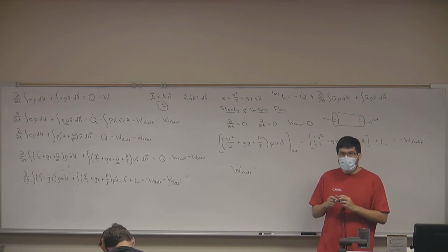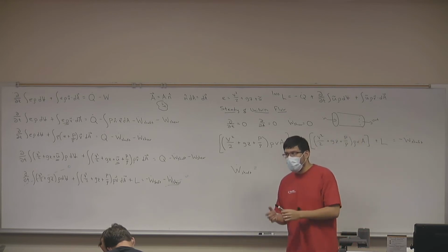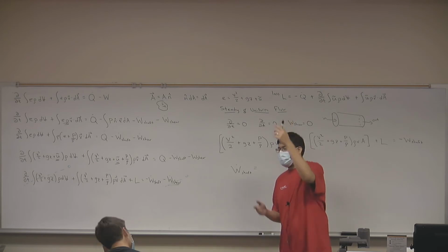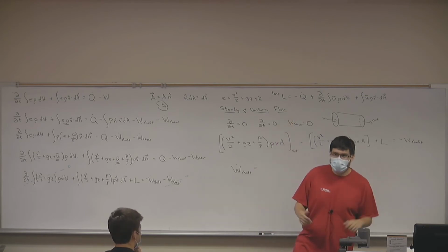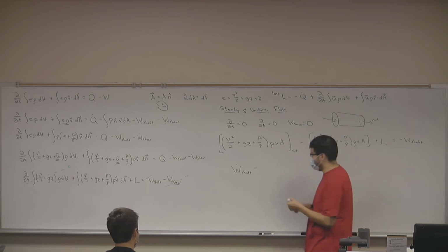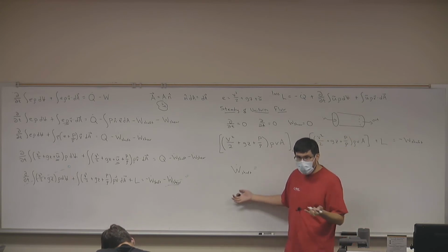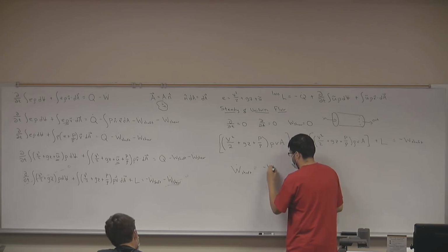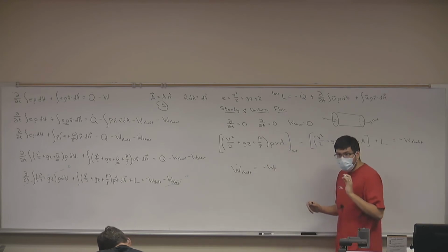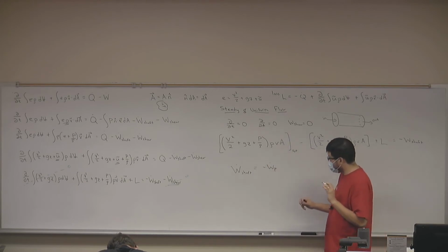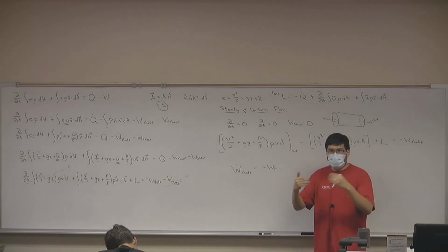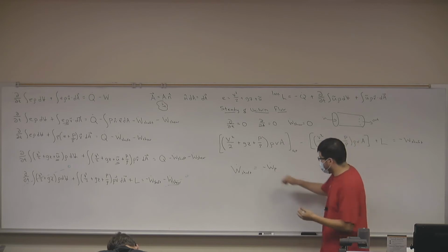Let's say I want to increase the energy of the water in my reservoir so it can be pumped. I used the word already. So it's pumped. I should have thought about it. All right, so our shaft work can be whatever's added to the system, which I'll just call my pump power. Okay? Negative, because we're using vector notation, where into the control volume is negative, out of the control volume is positive, so pump power.